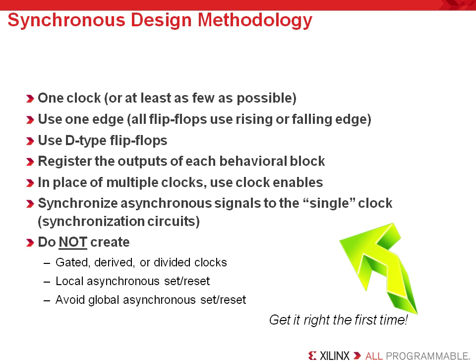To reduce the number of clocks, you should consider building with clock enables. This will save global clock resources and ensure design reliability. Registering inputs and registering asynchronous signals is important as well. If the clocks are unrelated, try to avoid metastability problems by using a synchronization circuit.